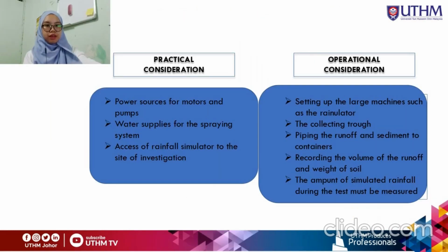When using the rainfall simulator, there are a few practical and operational considerations. As for practical considerations, to make sure the rainfall simulator works properly, a power resource, water supply and access of the rainfall simulator to the site of investigation are needed. As for operational considerations, we need to set up the large machine, collect through piping the runoff, record the volume of the runoff and weight of the soil, and lastly, the amount of simulated rainfall during the test needs to be measured.